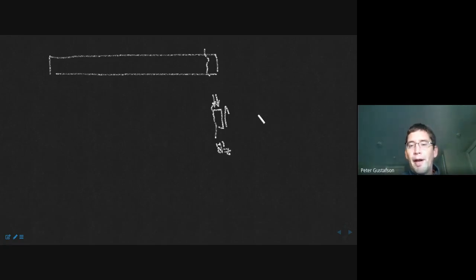And in this domain, of course, if we sum the force, well, that was a terrible sum sign here. Let me try again. Sum the forces in the y direction, they're going to be equal to 0. Well, V will only be 0 in the limit as dz goes to 0. Okay, and of course we recognize that we're going to drive that all the way up to the edge. And so at this point, if we were to complete this argument, I could say plus V at L.